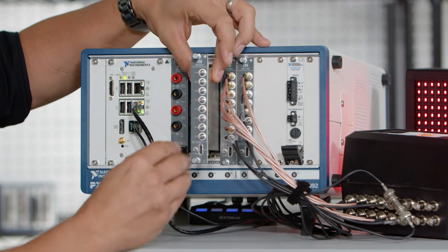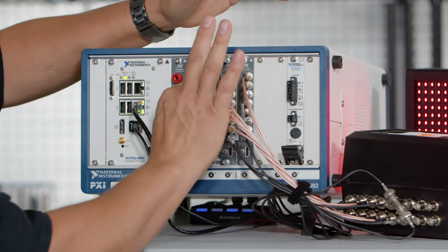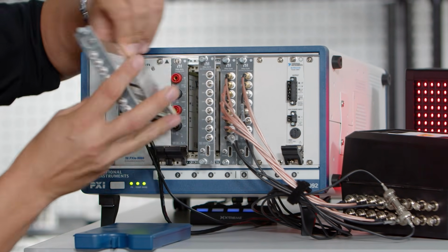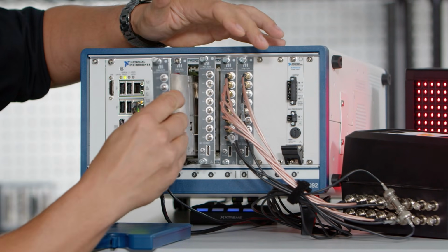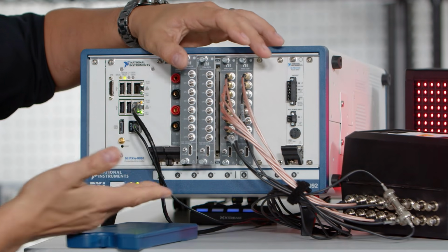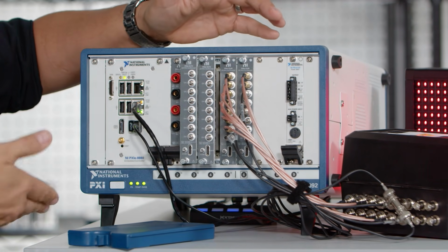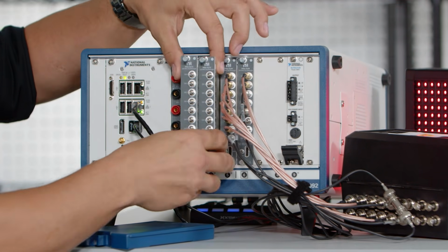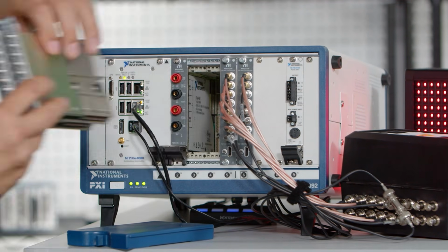And really, if we needed to go to a 24 channel scope, or even if we needed to go all the way up to, say, 32 channels of oscilloscope, make sure I get it in there right? These are not hot swappable, so I'm not going to push them in, but that's basically it. Shut down the system, plug in the slots, turn it back on, and take the exact same steps that you saw just a moment ago.